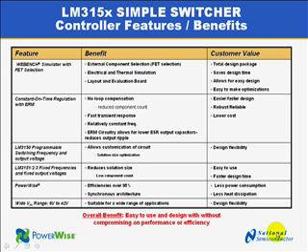The summary shows where the advantages of that new family are to be found. First, we have the WEBENCH simulator that lets you select the components, including the external FETs. It lets you electrically and thermally simulate your design. Then we have the constant on-time regulation that is used in this part. The advantage of that is it does not need any compensation, so that part is stable under all conditions, and it reduces the bill of material count, so the component count, to make a small design.